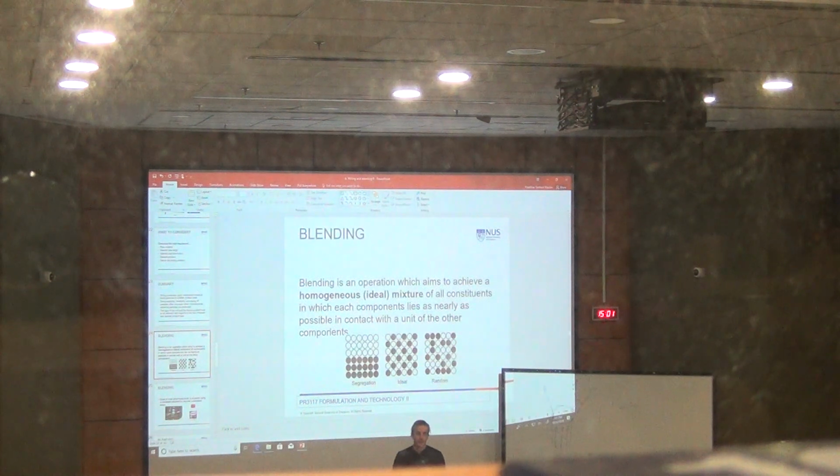What you should also understand is what can lead to particle segregation in this case. Here we discuss two different effects which are particularly important. The Brazil-nut effect: the big particles cannot really penetrate deeper into the powder bed, and this is why they just end up at the top. But at the same time, we also have the effect of gravity, which means there's also a tendency for the big particles to sediment in the powder, and this also can lead to particle segregation.